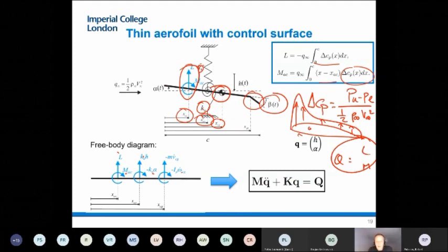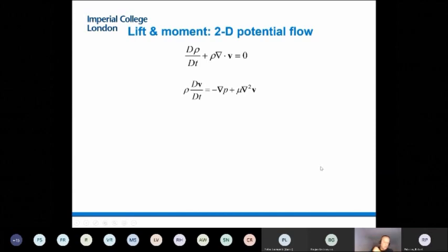So this is the second order differential equation that describes the dynamics of an airfoil on springs. The one thing which becomes tricky here is what's going on the right-hand side of the equation, the dynamic forces. When the airfoil moves and displaces, it is not just anymore that the lift is proportional to the angle of attack. We enter the domain of unsteady dynamics, and that's the one thing that requires a little bit of attention. So what I like to do next is to basically go through a quick summary of what things we actually need to consider when we are computing unsteady dynamics on airfoils.